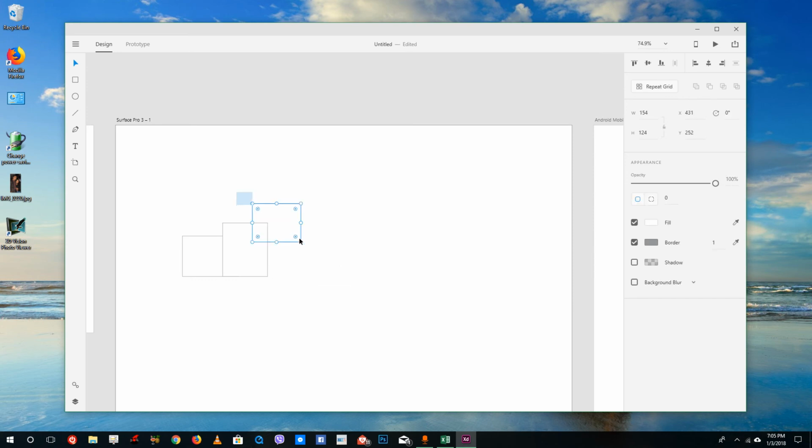What I can do with subtraction and addition is select two of the shapes just like this, and I can combine these shapes. If I bring in a third shape, I'm going to press Control X and Control V, so I have this shape on the top. Now I select this and select this to subtract it out, and you can see that my shape is subtracted. If I keep an oval, let me select the shape right here and then do intersect, and you can see that the intersection of the shapes happens right there.